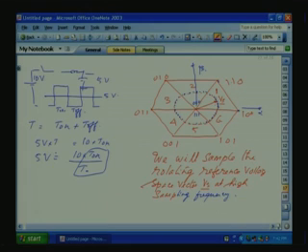So let us see how we can generate this volt second. Let us go to sector one. The same thing we can use for other sectors also. For other sectors, for a particular angle, alpha is the angle that Vs makes with the start of the sector. For other sectors also alpha will be the same, only the switching vectors are different.